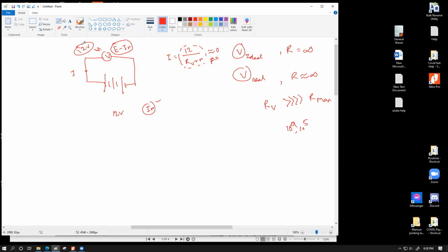You're going to get something more or something less. What are you going to get? This voltmeter reading should be what? Something less than 12. Exactly. If your equipment is really good, maybe you might get, let's say, 11.99999. Maybe after a lot of 9s there comes something other than 9. That's possible, but you should never get 12. Why am I telling you this? I'm trying to instill the idea in your understanding that using a direct method like this, we can never measure the actual EMF of a source. It is not going to work.